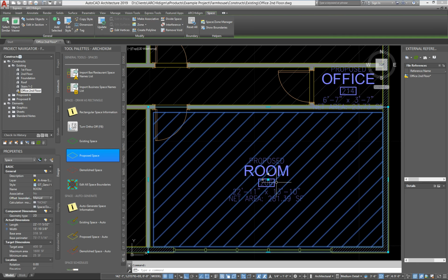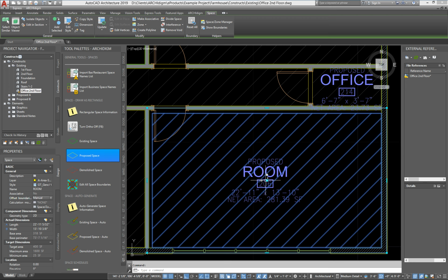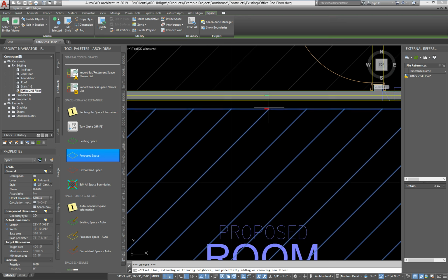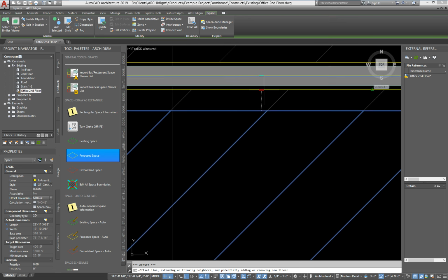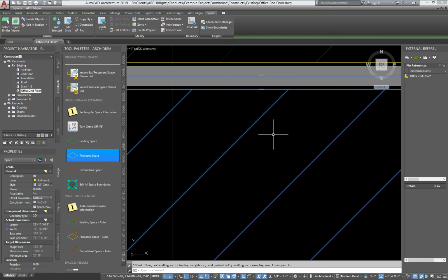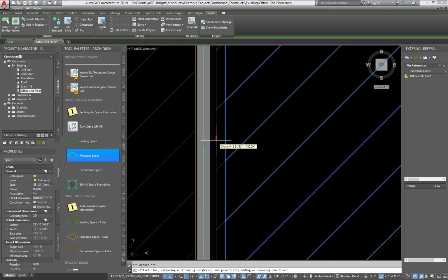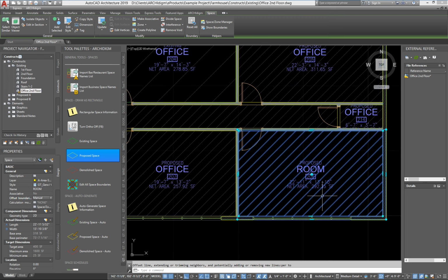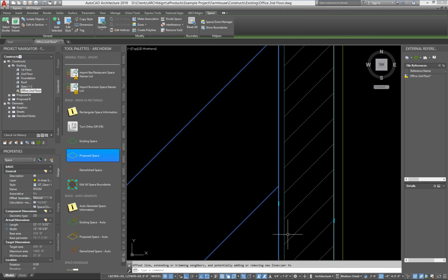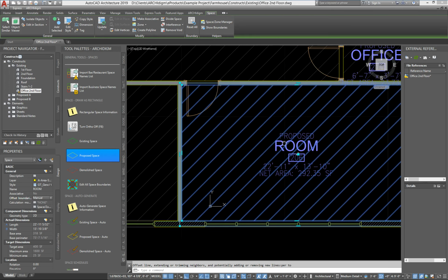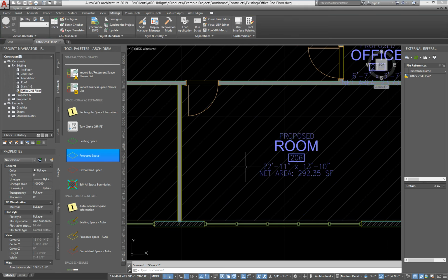Of course, you can do your own work. But I'm going to now change that. I'm going to activate the net boundary by clicking on that, and you'll see the grips appear. Now I'm going to pull the net to here and perpendicular on the inside finish material. So I'll do here to perp on this one, and I think I'm good on this one. Yep, so it was just those two, and then I can just exit out.